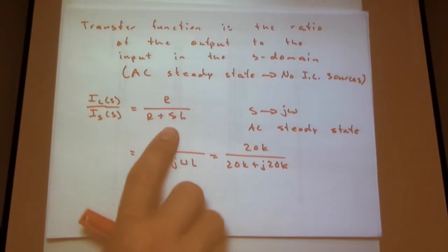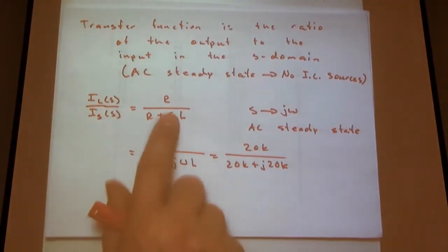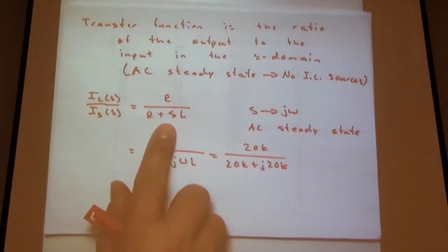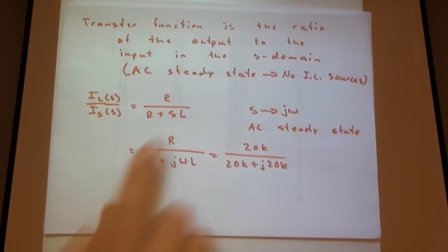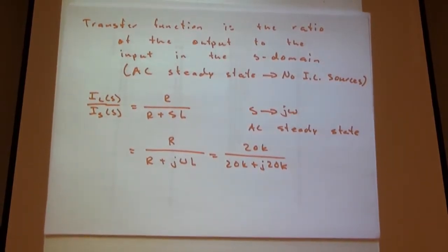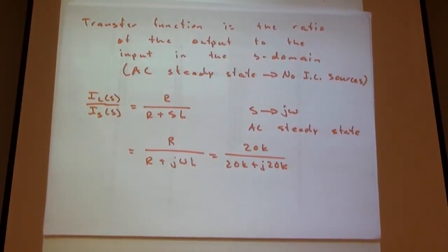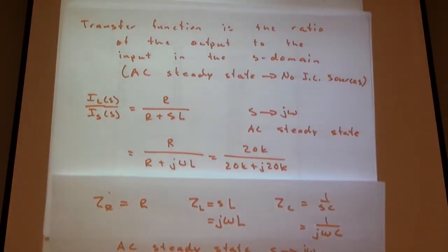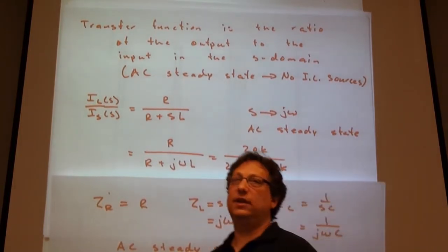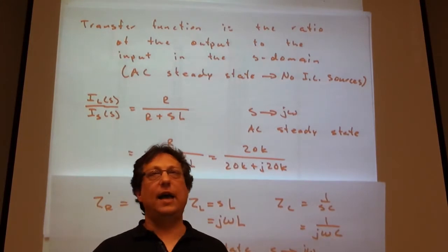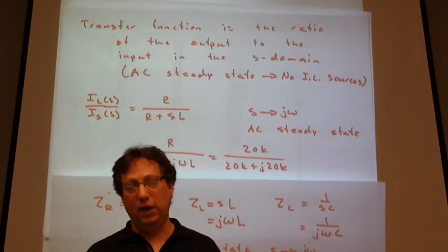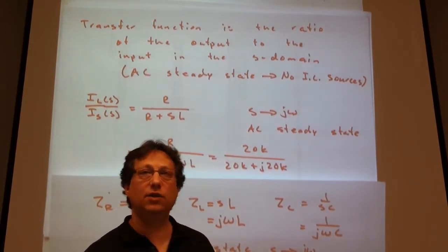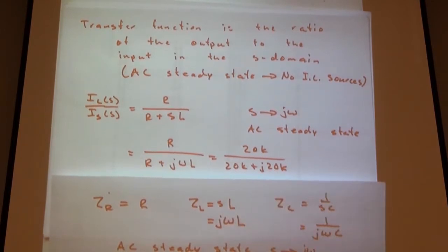But another thing, we can look at this and make some observational comments. So going back to one of our earlier slides, we've already brought this up a couple of times. As frequency goes to 0, how does an inductor behave? Well, frequency going to 0 is the DC term, so as we go to DC steady state, we know inductors are short circuits, and we see that right here in the expression.